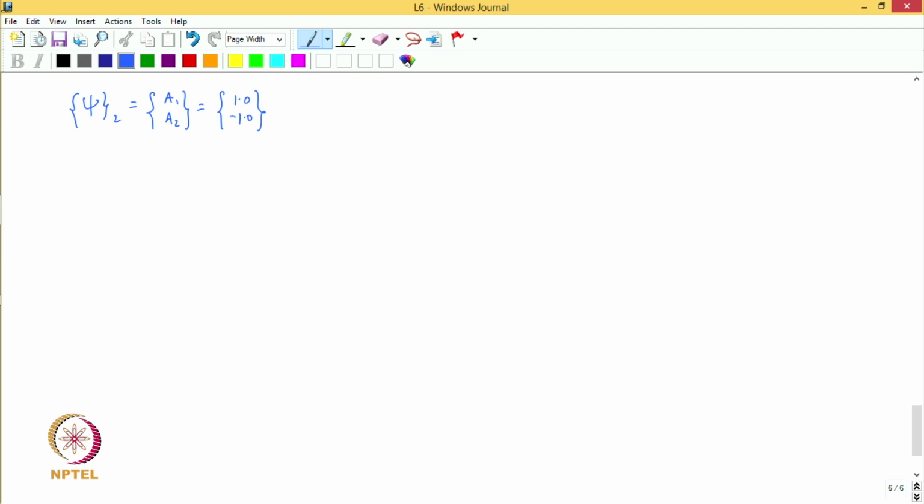So, effectively what is happening in the first mode of vibration, if we show the motion of the two masses on the y axis. I am going to show here x1 and x2, and let us say the two masses are here. The mass m1 has the same displacement as that of m2, like this.